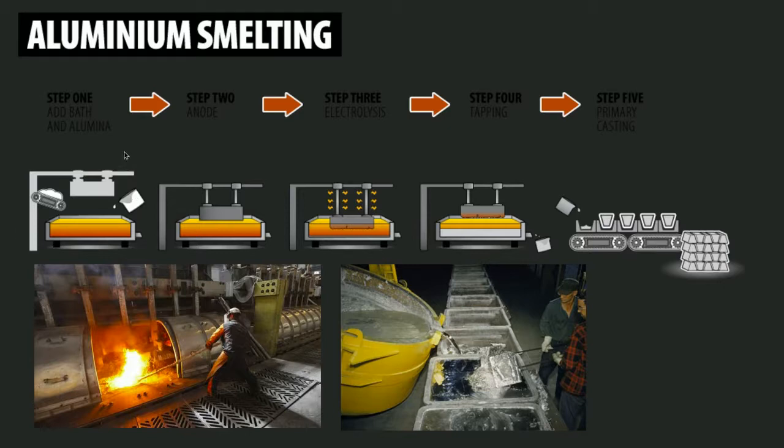Okay, so the way this process normally goes down is you start with your alumina, you heat it up to really high temperatures, basically enough to melt the aluminum ore that you end up with, and you mix that alumina into chemical solvents. And then you put it in a tub that allows you to force an electrical current through it, and you force electrons through basically this alumina dissolved in chemical solvents. And in the process of forcing electrons through, you change the chemical structure of these materials.